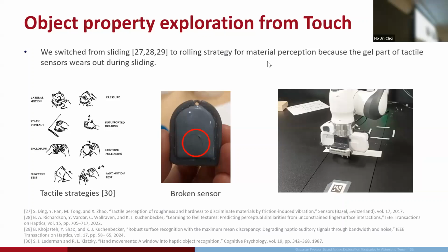And the other way, if we don't use the camera, there are capacitance-based sensors and also pressure-based sensors. I believe the capacitance-based sensors can have higher resolution. They're already using MEMS technology, but to me it still seems too big. So maybe using multiple of those MEMS chips might give better resolution.